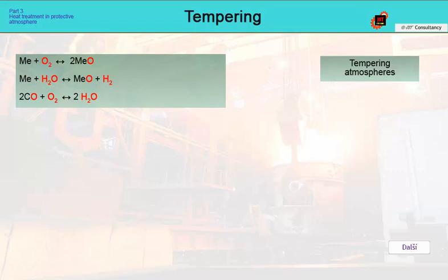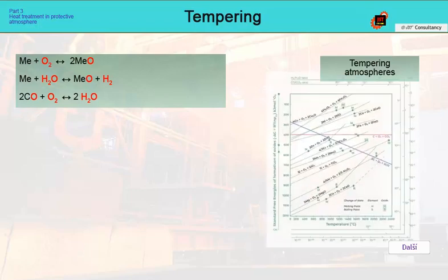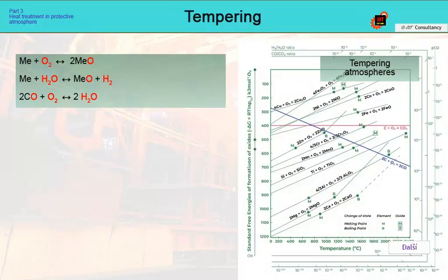When using pure gases such as nitrogen or argon, the oxidizing ability of the atmosphere is significantly reduced, but residual oxygen or water vapor is enough to discolor the parts from the oxides that form.